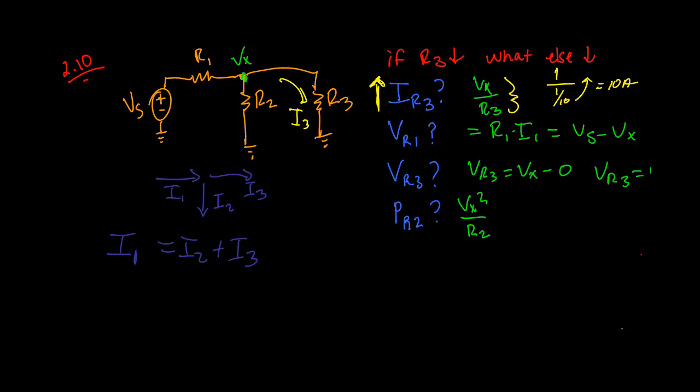So in this case, we know that the current through R3 goes up as R3 goes down, so I3 is going to get bigger. I2 is basically going to stay about the same, because as I3 gets bigger, I1 will converge to what I3 equals, so I1 will equal about I3. With that being said, if I3 goes up, so will I1, because it needs to be supplied from somewhere.